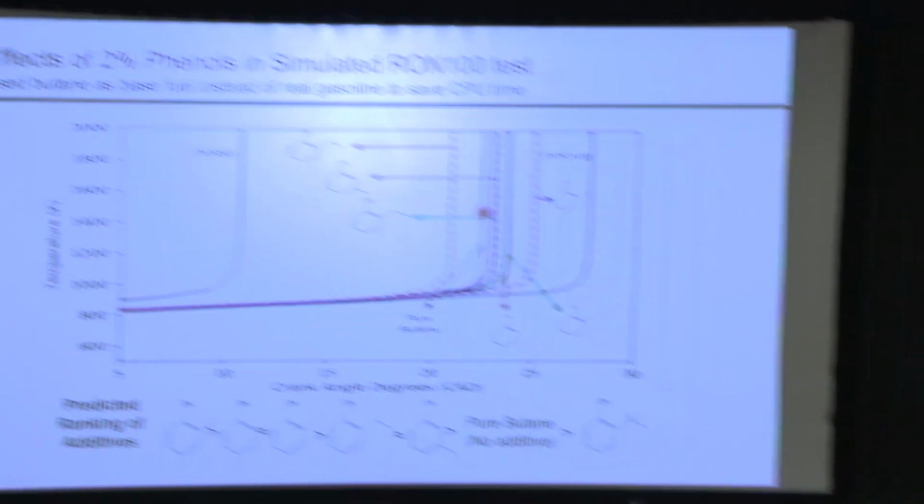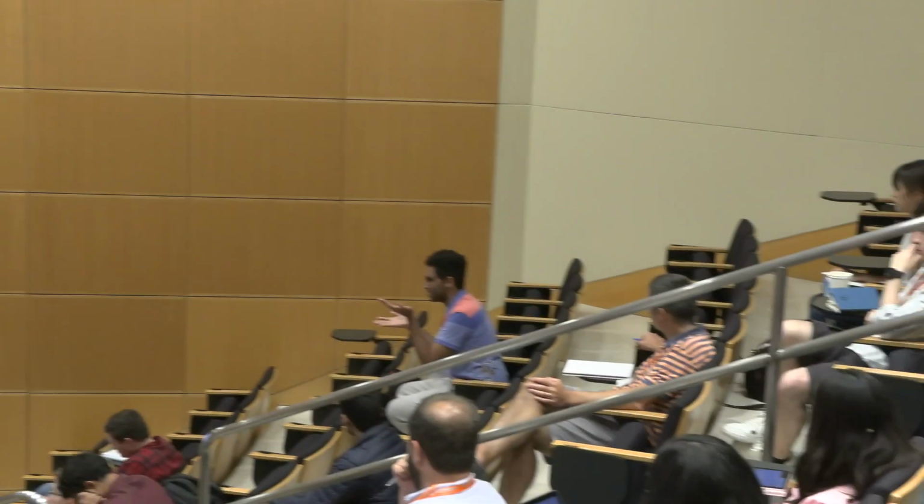For the comparison between the experiments in the engine and in your model, the ignition delay has a physical part and a chemical part. So the ignition delay that we got from the engine experiment includes the two things, the physical delay and the chemical delay. However, for your simulation, it's only the chemical delay. So is it fair to do this comparison, because in your model you didn't include the physical delay?